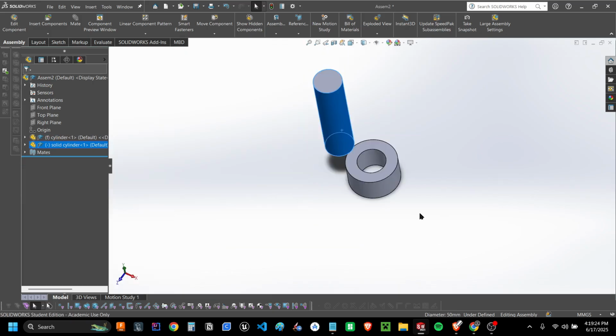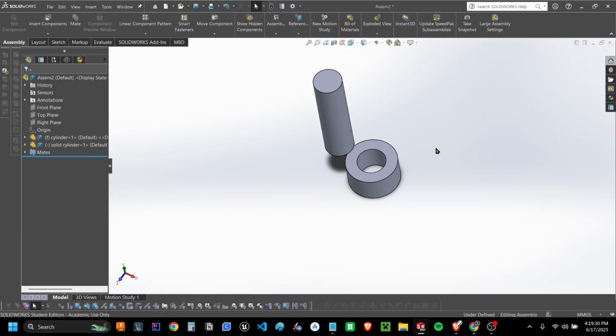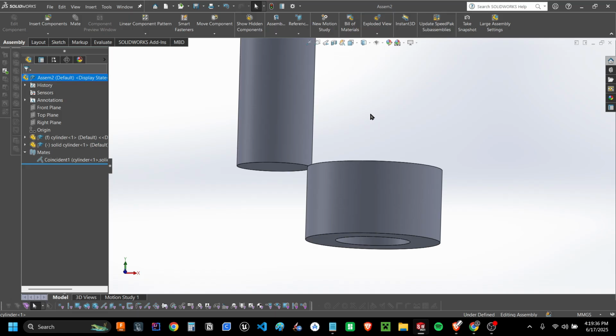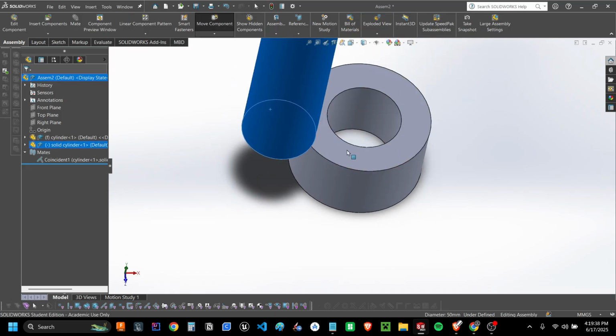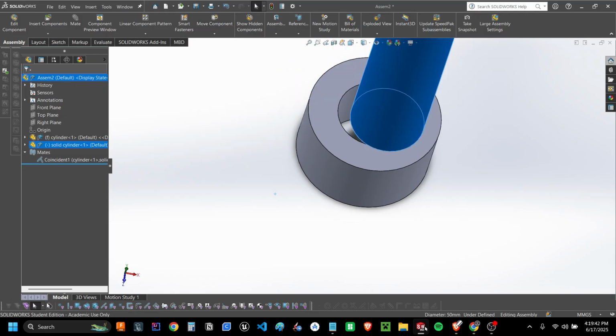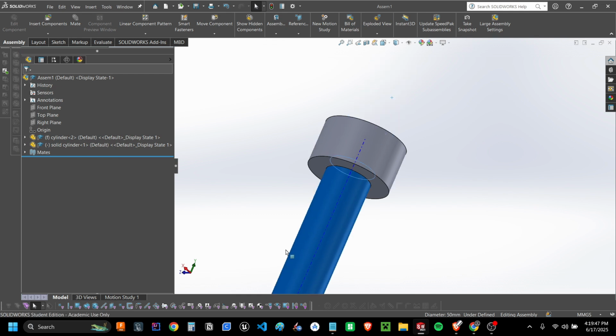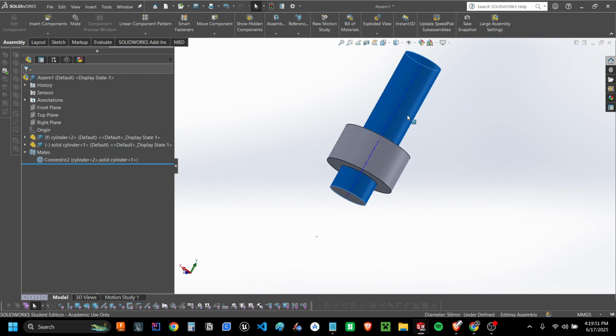Finally, I want to show you guys subassemblies. So right now I have two assemblies, this one which is called Assemb2, and I'm just going to save that real quick. And in this one, all I've done is apply one coincident mate to these two faces, so you can see that regardless of how I move it, it's still there, but I can still move it around. And the other assembly called Assemb1, where I've just made these two circular edges be concentric to each other, so I can still move them around.